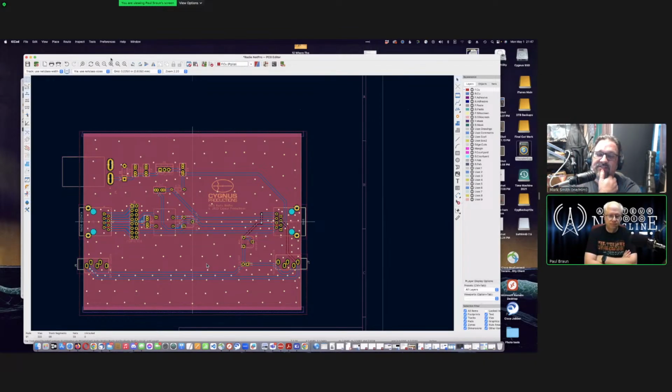Okay. That's the way I did it for the longest time before I wanted to bother figuring out how to export Gerbers. If you export the Gerbers by hand, it's kind of a manual process. You've got a bunch of exports you need to do, and then you need to zip it up and then upload it. So doing it by hand is kind of a pain in the ass, and that's why OSH Park was really nice, because you could just upload the one file, and they would do all the exporting for you.